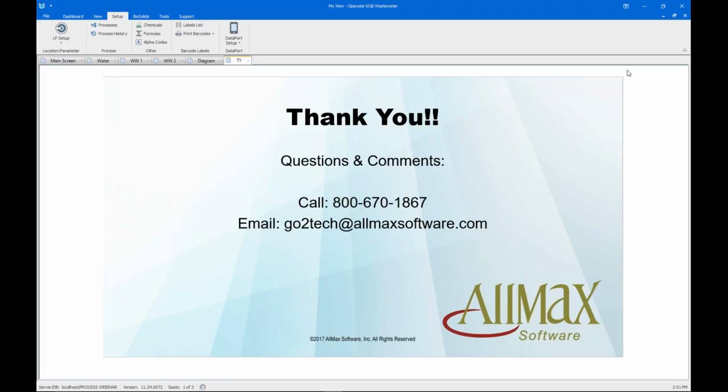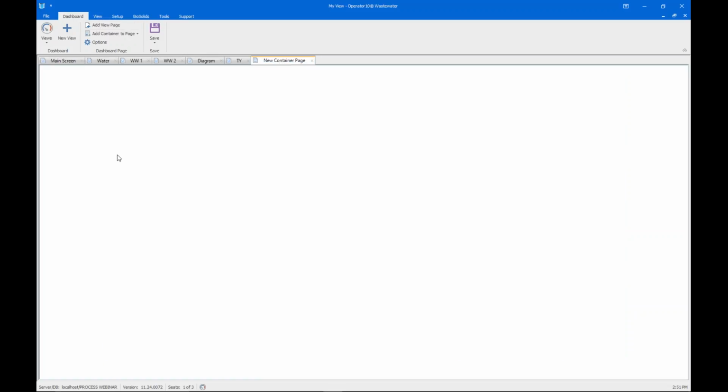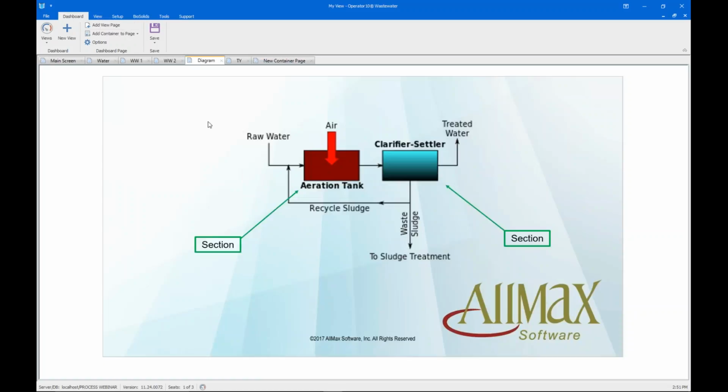And so with that, again, we have questions and stuff. One of the questions that I have coming in is somebody asked how to add an image to the dashboard like I've done here. This is actually fairly simple to do. I can show you this real easy. It's not covering what we're doing, but to add an image to a dashboard, you go into the view and you have your dashboard and you want to put an image, kind of like I did with our plant diagram, one of the benefits of which is I can then put hotspots on this if I want to.